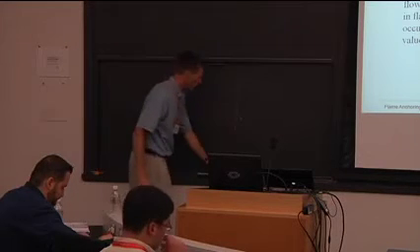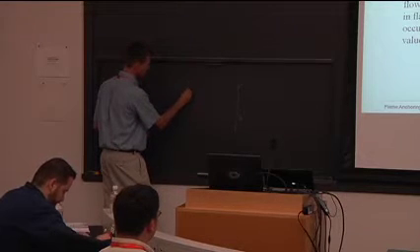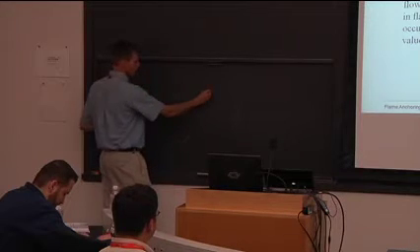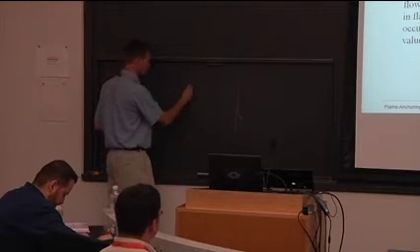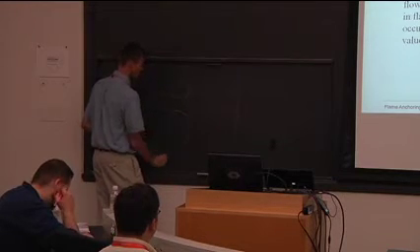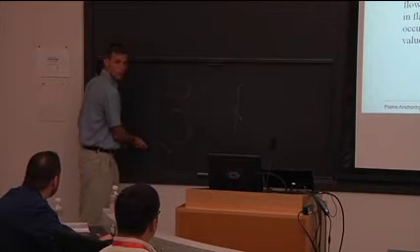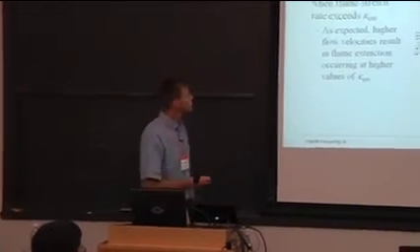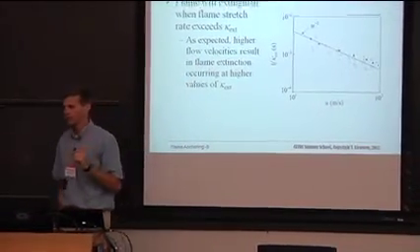So, for example, in hydrogen flames, which have positive Markstein lengths, DNS simulations often show flames that look like this, where this is reactants. So basically, this is the highly curved leading edge of the flame, except I had it backwards. This would be a lean propane flame. It would look like that. You can see accelerated burning right here, and the flame actually extinguishes on the tail end. It's just too curved. Anyway, the flame will extinguish when the flame stretch rate exceeds what I'm going to call kappa extinction. Kappa extinction is the extinction stretch rate. And you can compute it.